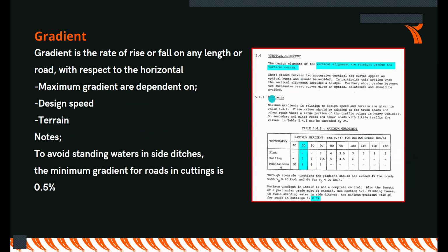There's also the gradient. So we control the gradient. The gradient also, we said that it controls the drainage of transport. Of course, it's pegged to the terrain. So if the terrain is too steep, then there is an issue with drainage. Then there's nothing you can do because terrain is supreme. If you want to do a lot of excavations, then it means you need to invest a lot of money to make sure that you cut away material to probably achieve some gradient.